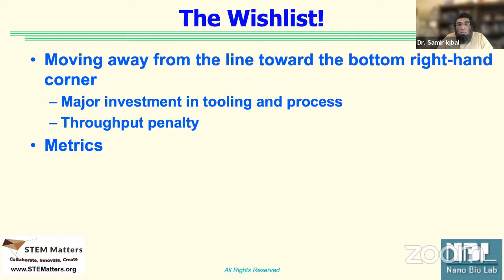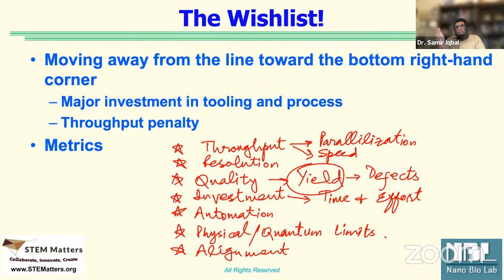Now, I want to automate, which means I want equipment and systems that can detect those anomalies, or during the process can set things up right. Which means precision in robotics. So it's a whole bunch of things that we can do. And when we make things too small, we reach physical limitations. For example, we have talked about the transistor and the thin area where we make the oxide called gate oxide. If you make it too thin, it stops being an insulator. Yes, it is an insulator, but then the current starts tunneling through the oxide.